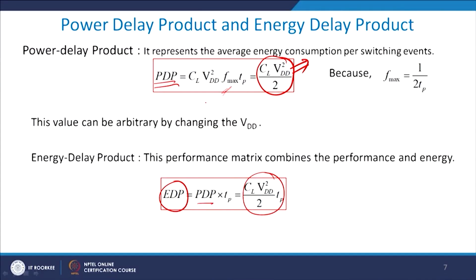You can also operate at lower frequency operation. So, in most of the cases when you do not want the power, you do not want a very high frequency of operation, you can actually afford to keep your F max low. Once you do that, your PDP as well as your total power actually reduces drastically, right. And so, these are the few things which you should keep in mind as far as designing is concerned.